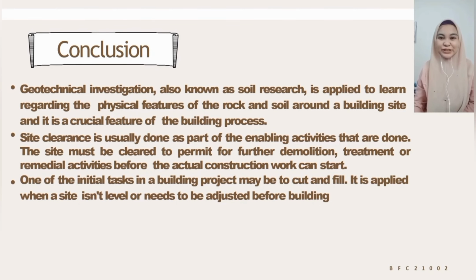As a conclusion, geotechnical investigation, also known as soil research, is applied to learn about the physical features of the rock and soil around a building site, and it is a crucial feature of the building process. Site clearing is usually done as part of the enabling activities. The site must be cleared to permit further demolition, treatment, or remediation activities before the actual construction work can start. One of the initial tasks in a building project may be to cut and fill. It is applied when a site is not level or needs to be adjusted before building.